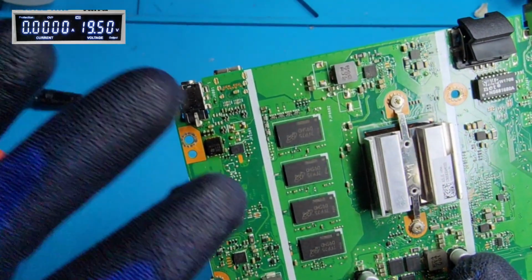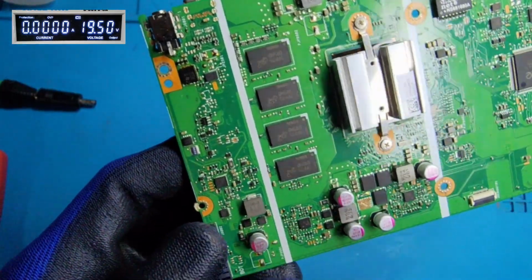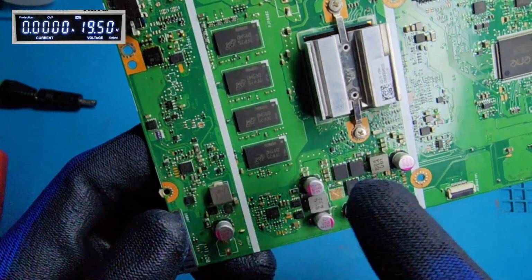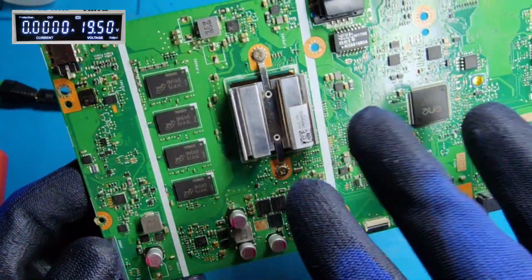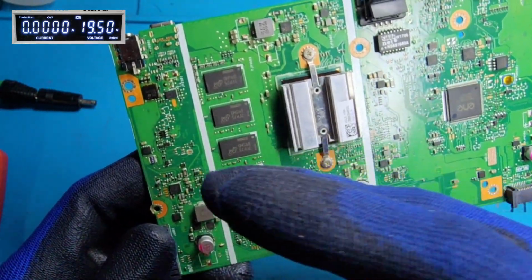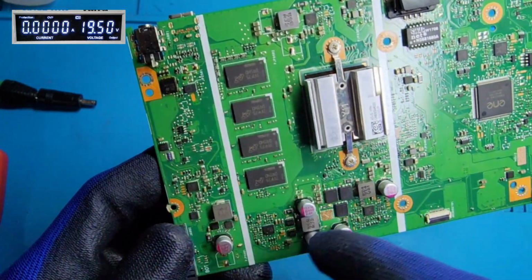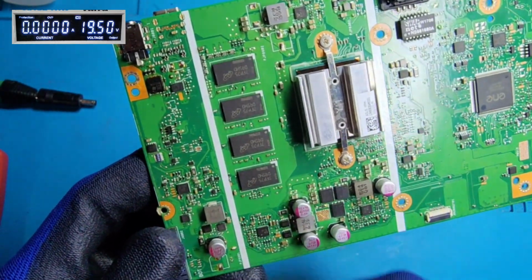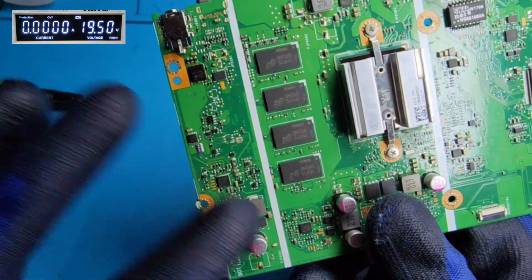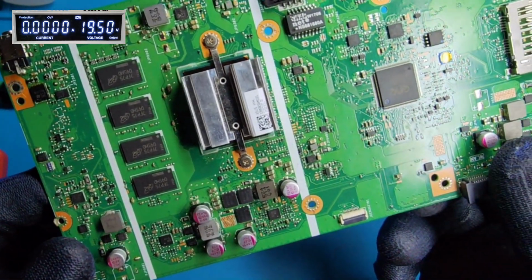But do not always short the first MOSFET by using a jumper wire, because the charger IC is there to protect your components in your motherboard here. So it is like a gatekeeper. If any thief comes inside, it will block it. So if there's any short on your motherboard here, then the charger IC will not provide the gate voltage for the first and second MOSFET, and the main power rail will be absent.